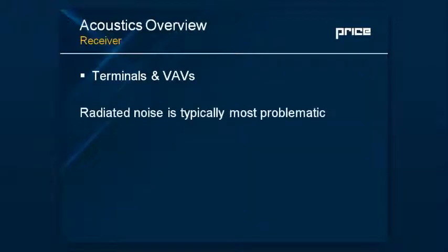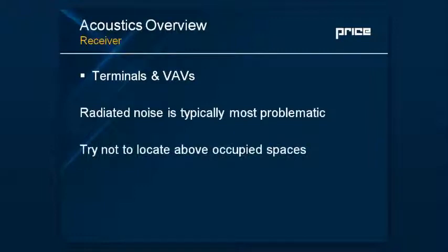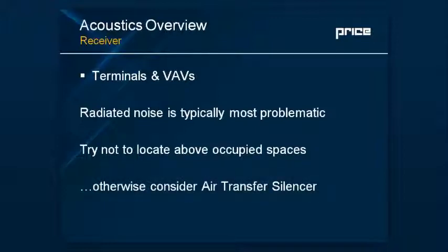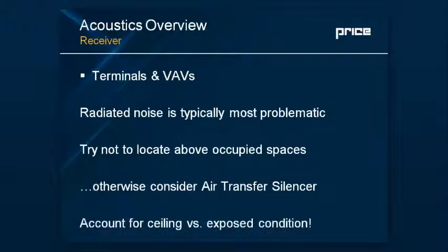In terms of terminals, a good rule to follow is that radiated noise is oftentimes the most problematic, and typically you don't want to locate these above occupied spaces. Otherwise, you might want to use an air transfer silencer.